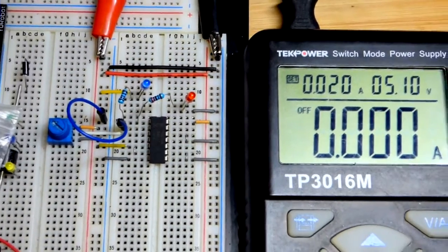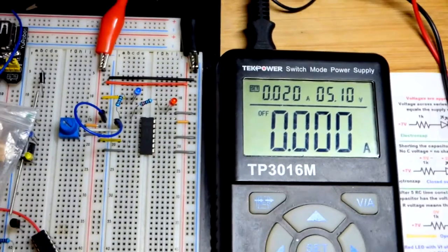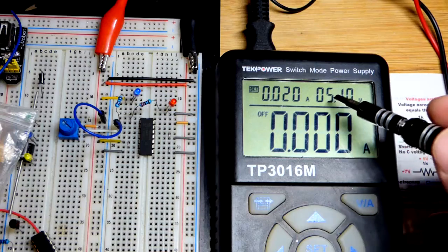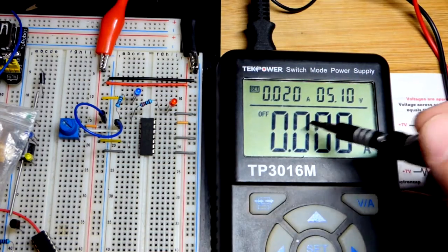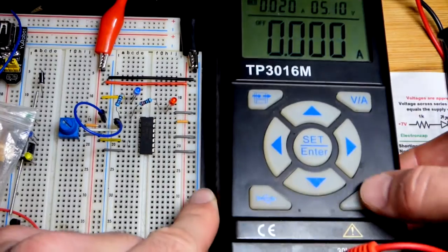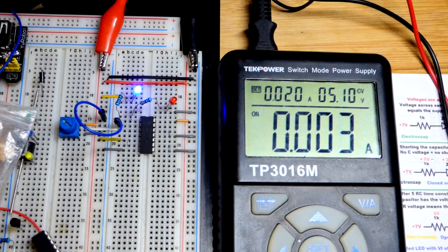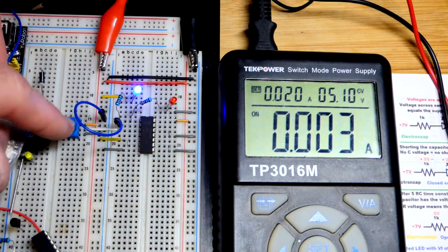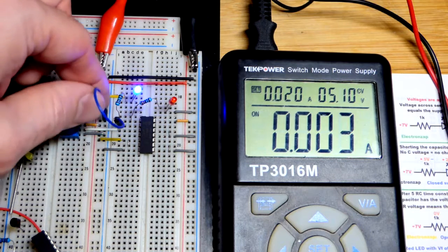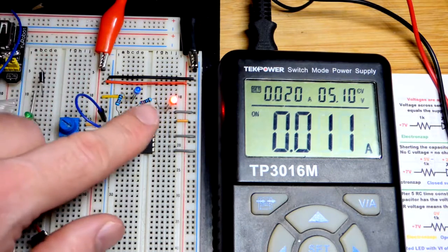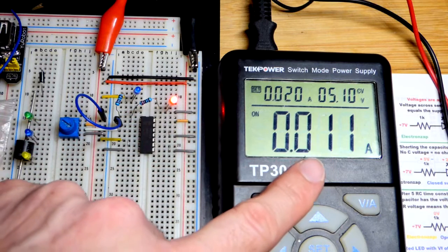So hopefully the light is better there. Right now the output's off. I have it set to 5.1 volts, which should still be safe for probably all of these 7400 series integrated circuits. I'll hit the power button, and now the power is on. So as we said before, for the output to be high, both of the inputs have to be low. And so we know that one or the other is high. I can see this jumper is low, and that one's high. If I go low now, you can see it's high. And as I said before, the red LED is not as bright.